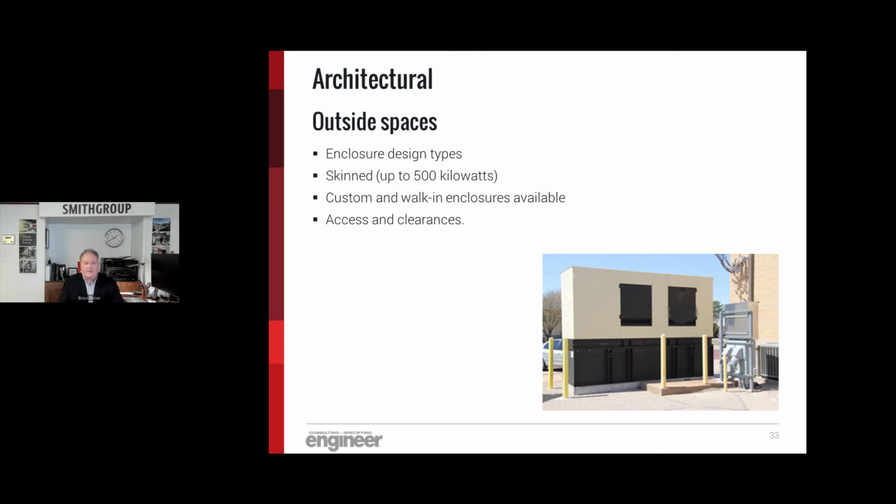In this photo, you can see a pretty high belly tank. You're really going to have to consider how will they get to the generator up above to do servicing, testing, and inspection. Often on larger generators, we build a platform around that belly tank so that you can get up and do the servicing. Skinned units are available from the vendors, typically up to 500 kW or more on the generators.